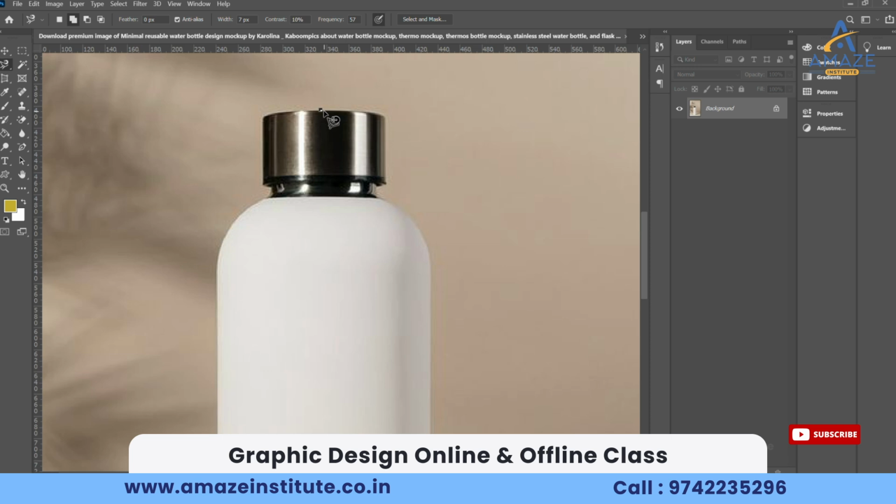After that, I don't need to click anything. Just like that, if I hover the mouse towards the right side, automatically the points will be created. I'm just hovering the mouse over this outline. It is not mandatory that you hover the mouse accurately. Just roughly hover like that, and it will be selected. Further, if you want to refine the selection, you can refine it with the lasso tool.